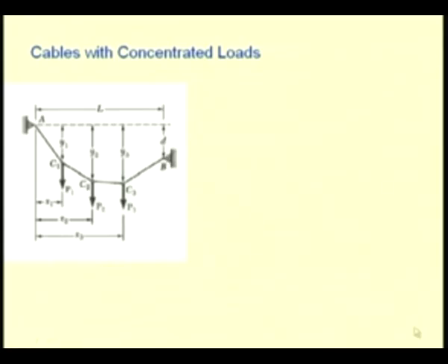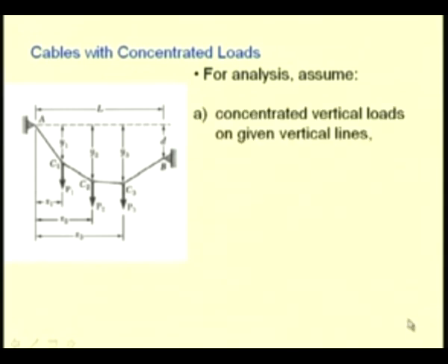Certain things we can note: for analysis we assume that these locations are given, that means the horizontal spans x1, x2 and x3 where these loads are applied to the cable are known. Also we assume for the current analysis the weight of the cable to be negligible when compared to the concentrated loads.